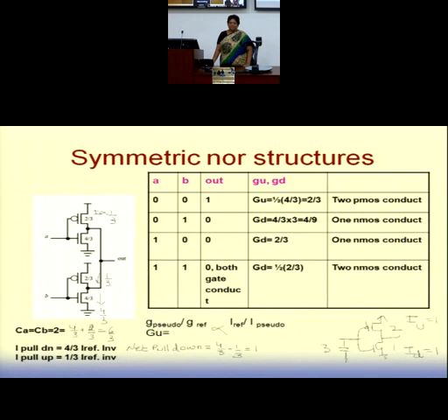Okay, first of all, understand the operation. This is actually designed by using static CMOS, but giving you a pseudo NMOS kind of operation. Why am I saying that? Because when discharge is happening, at the same time there is a charging current also. So it is giving you a kind of pseudo NMOS operation, but designed with only static CMOS. This is known as symmetric logic, not a symmetric gate. You can design any gate in this world by using only static CMOS inverters, but with proper ratio.